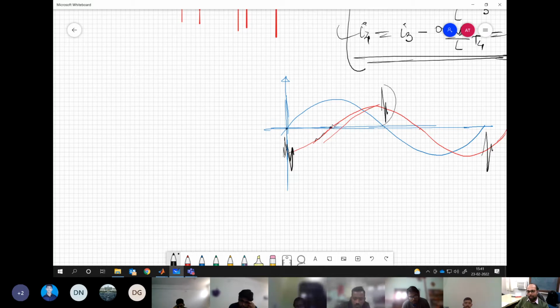So here it will be minimum because you are trying to realize the maximum voltage. Here also it will be minimum, and then in between it will keep increasing and it will be maximum here, then gradually reducing, and then it will increase again to maximum. This kind of pattern you will see in the current ripple on the motor current or somewhere, whichever you run with this kind of PWM. You understand what I'm trying to say?